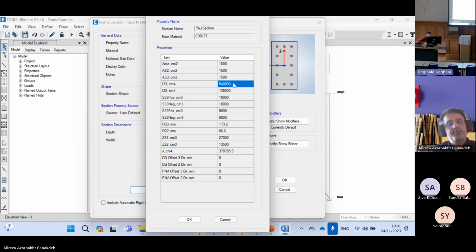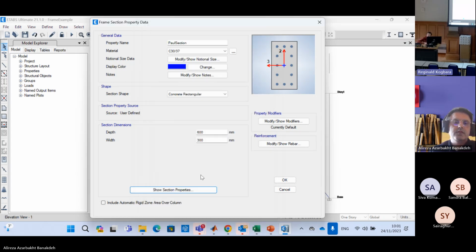Yeah, but is that always the same whether it's a composite material like reinforced concrete, you mean? Of course, the true answer to your question is no, it's not. But we assume that because we don't take the reinforcement effect into the calculation of the second moment of inertia. This is advised by all the codes.